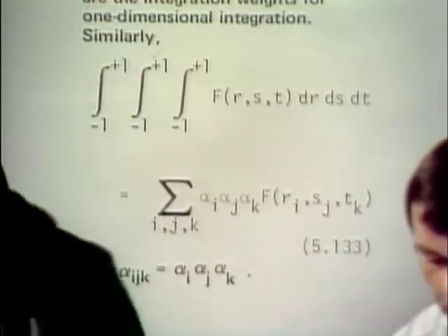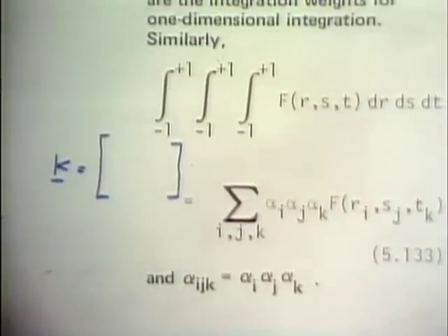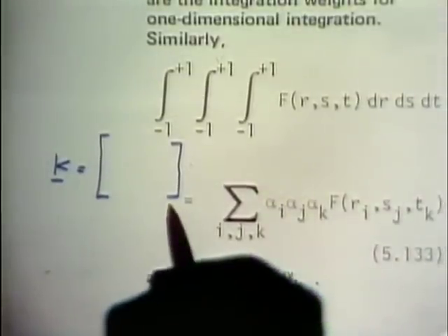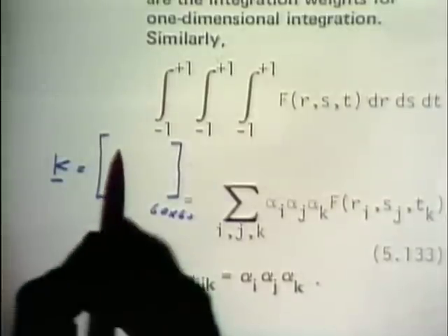I should also mention at this point that when we talk about an actual stiffness matrix, of course we talk about an array n by n for a 3-dimensional element, say a 20-node brick. This would be a 60 by 60 stiffness matrix, and every one of these elements here in that stiffness matrix would be an f, such an f. Every one of these elements would be integrated as shown here.